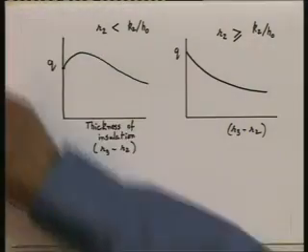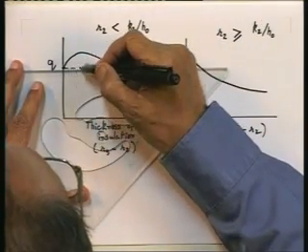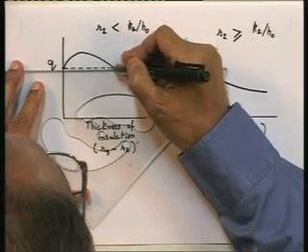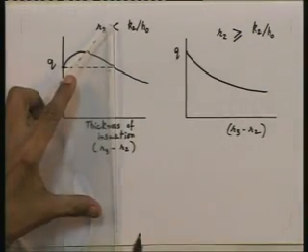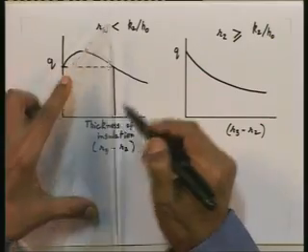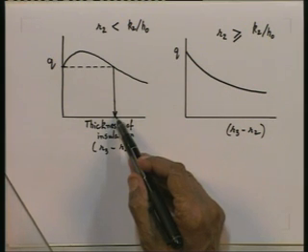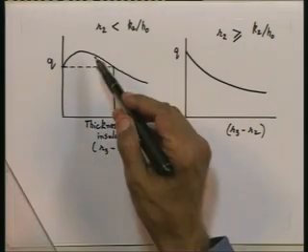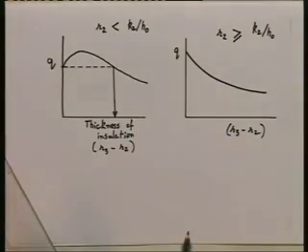You understand? So, if I were to take a horizontal line from here, what I am saying is if you have a situation in which R2 is less than K2 by H naught, then you should always put a thickness of insulation greater than the value shown by this arrow. If you put less, you will in fact get a value of Q which is more. So, adding insulation will hurt you, will not help you. You got it? That is the meaning and that is the sum and substance of what we are trying to do when we talk about the critical radius problem.